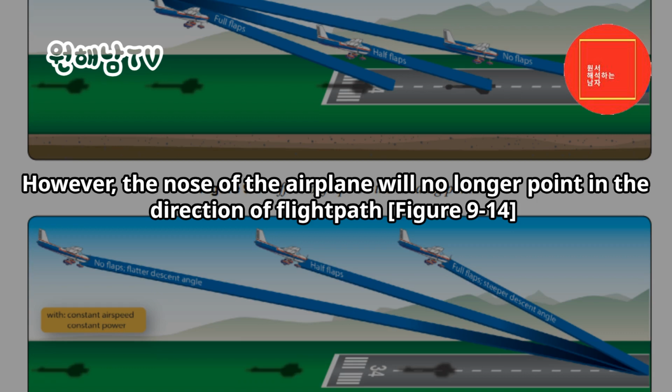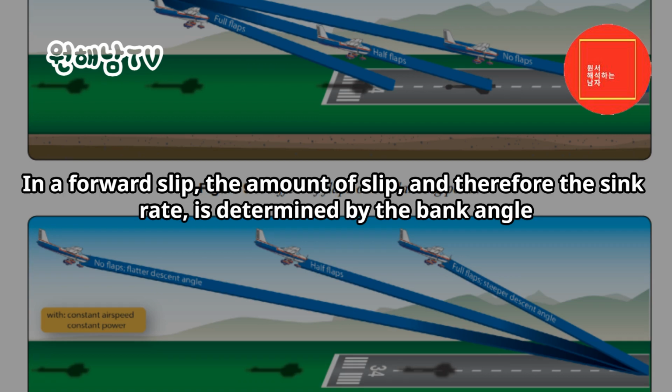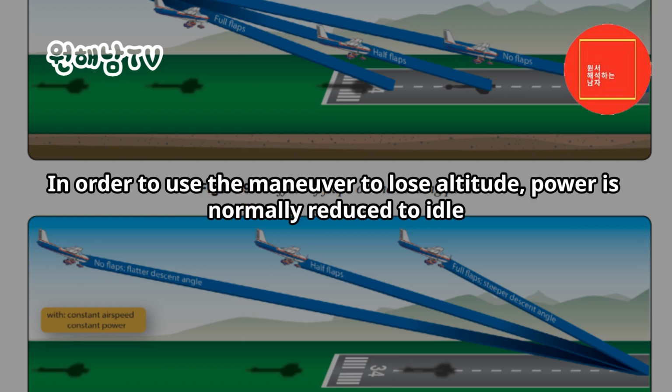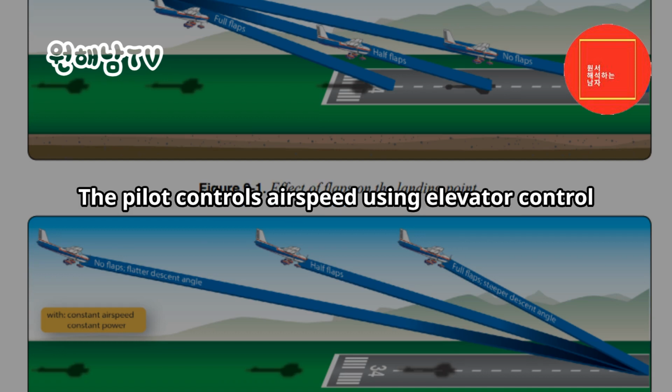Figure 9-14. In a forward slip, the amount of slip, and therefore the sink rate, is determined by the bank angle. The steeper the bank, the steeper the descent. In order to use the maneuver to lose altitude, power is normally reduced to idle. The pilot controls airspeed using elevator control.